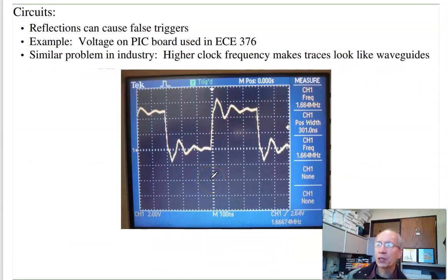You see that on circuit board traces. If I just have a wire on a circuit board trace that just ends, that's a reflection. You see that right here. I give it a step wave input. That causes waves to travel back and forth on the wire. Those reflections cause bouncing. If that bouncing gets too large, it passes through logic level 1, and I get pulse triggers. To stop that, I need to add a characteristic impedance, meaning a resistor at the end, to stop the reflections.